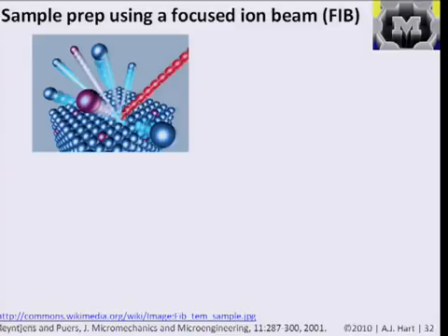So one way that other types of samples are prepared: say you have something that's like a little block that you see in the SEM, and you can't necessarily put it in a liquid and shake it up and throw it on the grid. Say you want to look specifically at one place, take a little slice, and then shoot the electron beam through that slice. It's really hard to do that, but it's possible if you can essentially machine the material at the nanoscale. One way that's done is using a FIB, which stands for focused ion beam. This model schematically shows the idea of hitting your material with a high energy beam of ions and throwing atoms you don't want away. So it's kind of like an ionic nanoscale water jet.